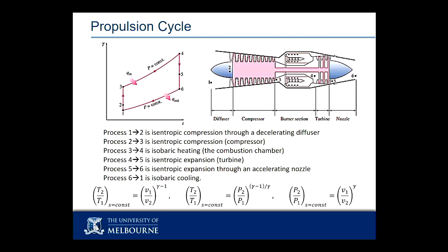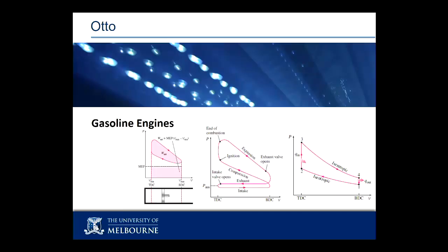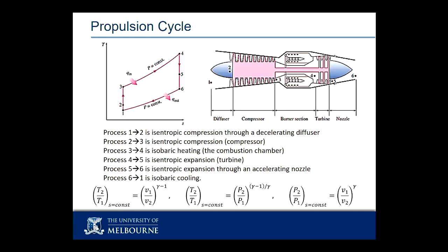So that's how a gas turbine flies. That's how it provides thrust. I need a difference between the momentum coming in and the momentum going out, which comes from, even at a constant mass flow rate, that only comes from a delta V. So I shouldn't have tapped as I was making that last point.